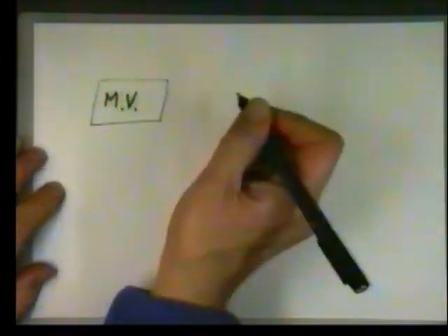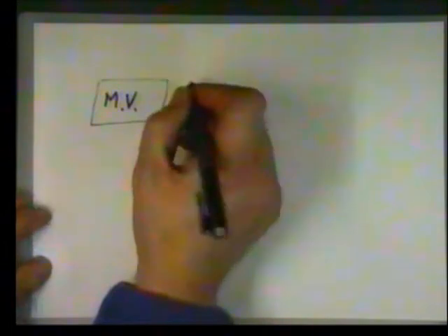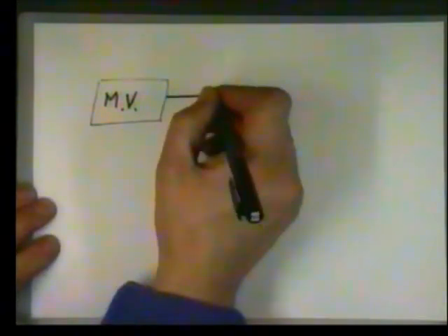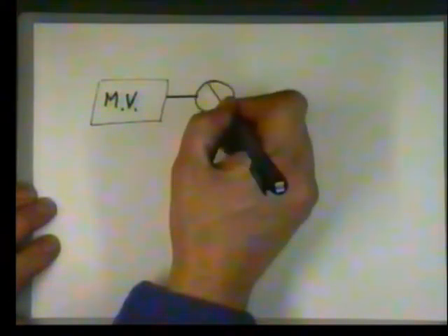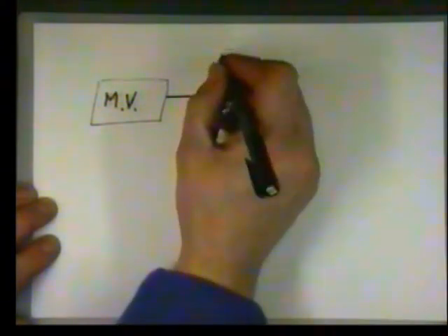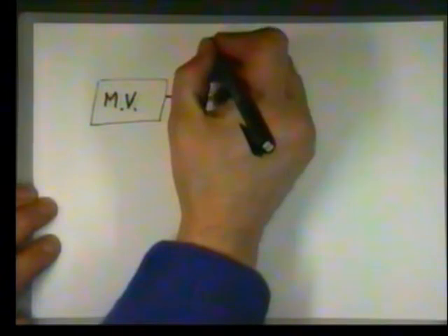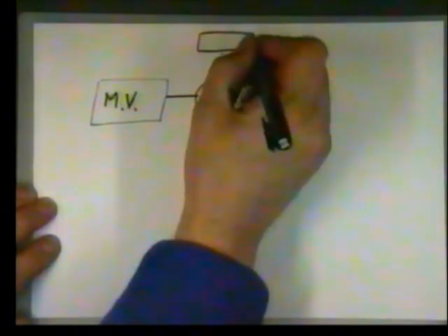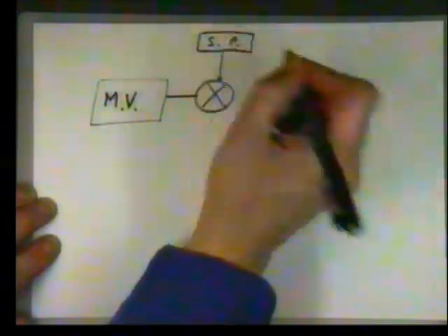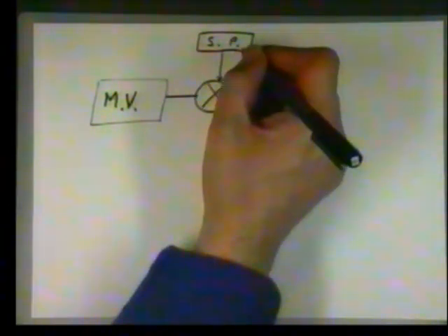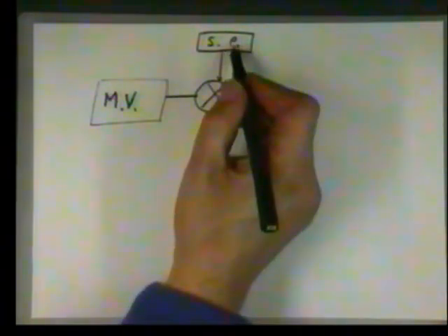That's coming from our transducers, our ADCs, etc. The other input we will have is a variable known as SP. That's our set point. That's what we adjust. That's the control dial, or what we dial in the keyboard. So that's what we want.